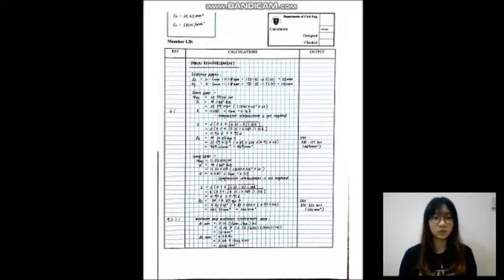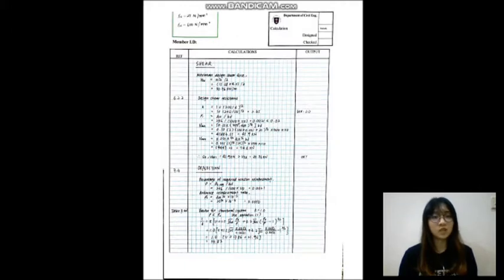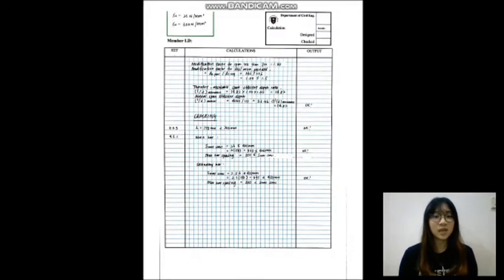And the shear check gives a conclusion, which is VRd,c, 45.9 kN, is greater than VEd, which is 13.76 kN. The actual span effective depth is 36.36, which is smaller than the allowable, which is 45.82.